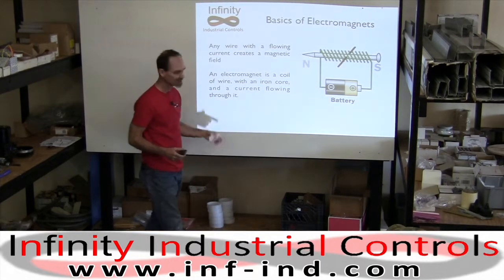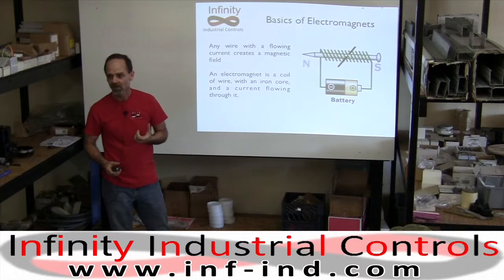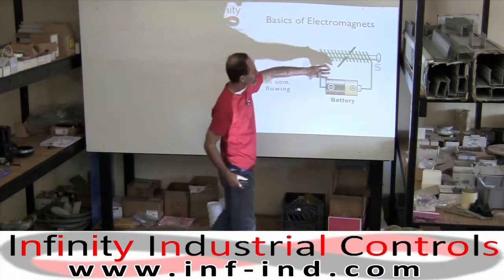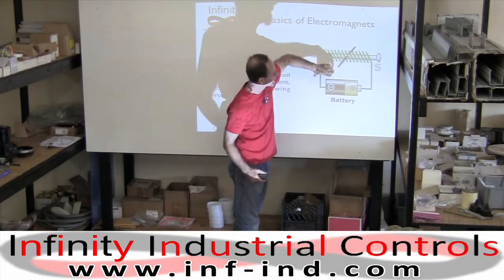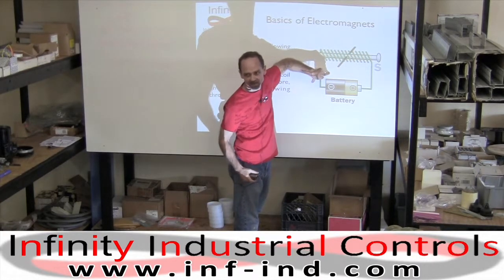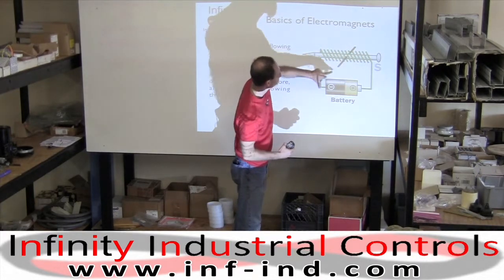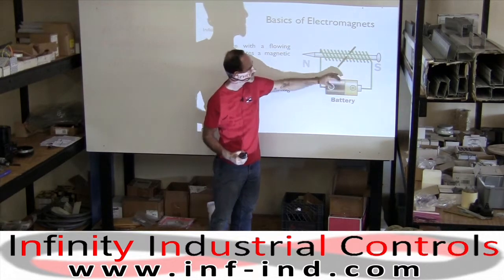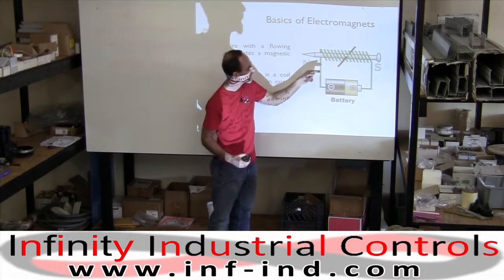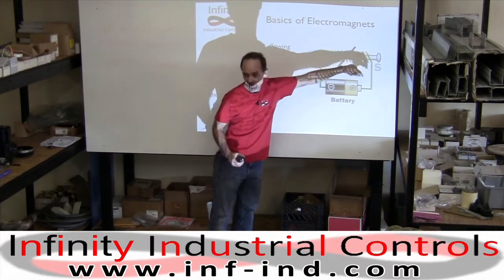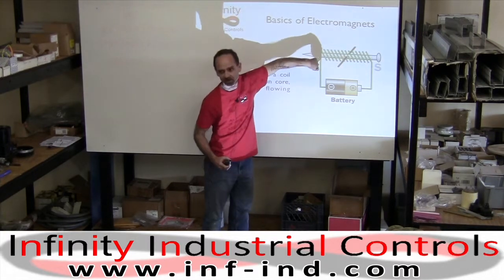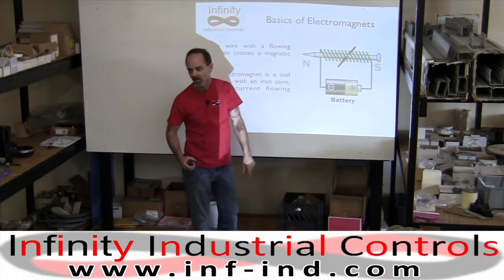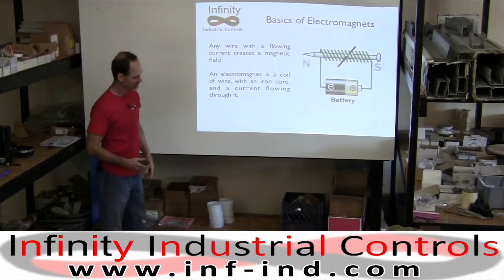One of the uses for those things I was talking about, the diodes earlier, the one-way gates, they'll hook them across here so that they're not conducting normally. It'll be in the closed valve state across here. That way it protects the supply side. When you disconnect this, since it induces in the opposite direction, it'll flow through the diode instead of whatever you're supplying. They call those flyback diodes.